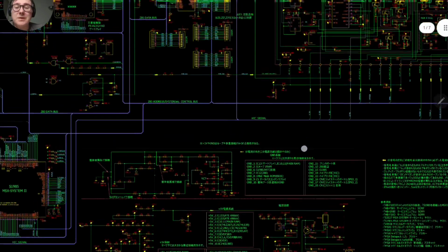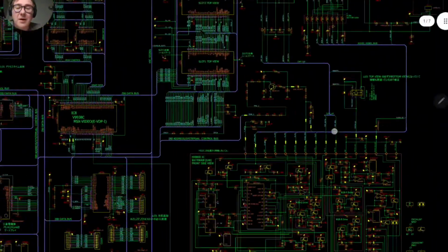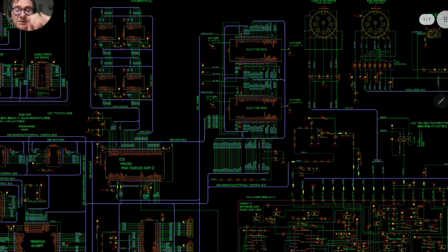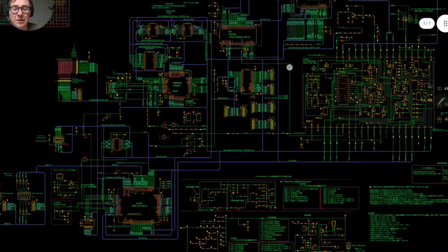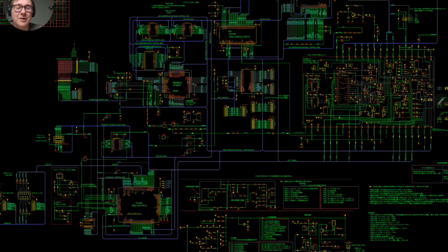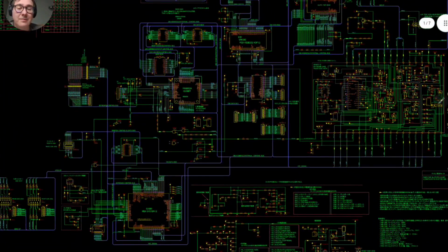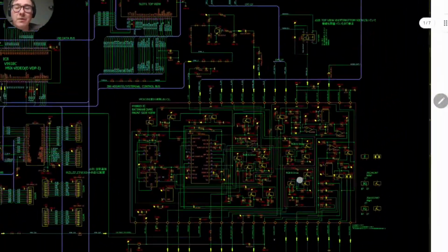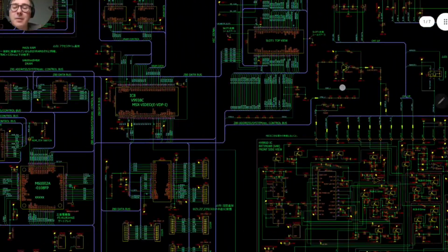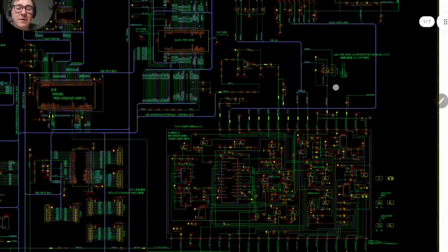Maybe the electrolytic capacitors, of course, not every capacitor, because these capacitors can leak the electrolyte into the board, and this is something that you don't want to happen at all, because this electrolyte is very corrosive and can actually destroy your board. I'm looking for the small board that is used for video conversion.